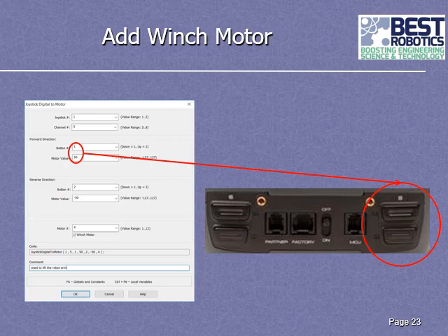So as you can see, the button number 1 says down. If you look really closely, you'll see a U and a D on those 2 different buttons. There's an up button and a down button. The first button we're going to configure is number 1, which is the down button. And for this one, we're going to tell the motor to move at a rate of 50. Since the range of values that you can put in here is minus 127 to 127, what that's saying is it's going to be moving in the plus direction at a little bit more than a third of the speed with which that motor can go.